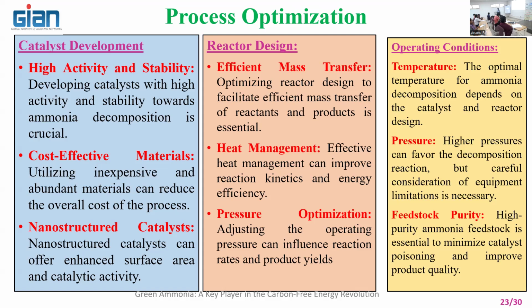Then the reactor. The reactor needs to be designed so that there is not much energy loss, that is, heat loss from the reactor. That's why we said microwave is going to be better than other types of process, because the heat is generated inside. The heat loss is going to be from inside to outside. So the system is highly insulated, and the heat loss is going to be minimum.